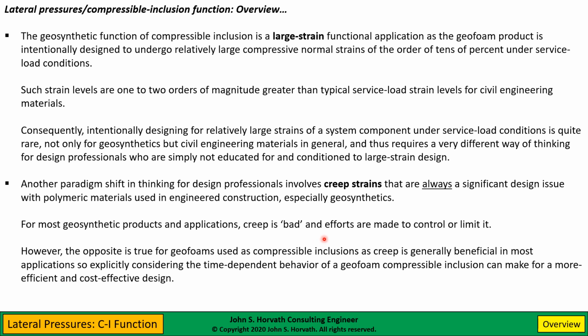And I mention this because, and I'll elaborate on this later on in the presentation, too often we focus on using material properties for relatively short-term rapid loading. And certainly we should be considering that this material is going to be in the ground for decades. We should be looking at the longer-term creep behavior because it can make for a more efficient and cost-effective design. As I said, when it comes to compressible inclusions, creep is your friend, if you will, and we should take advantage of it.